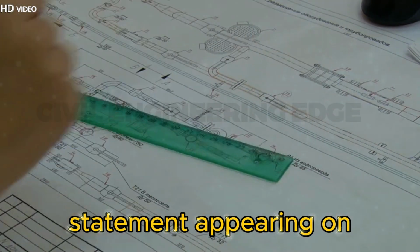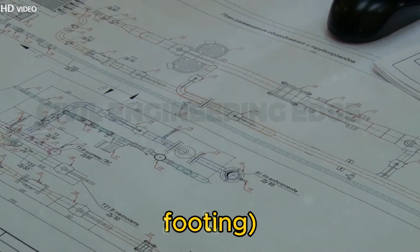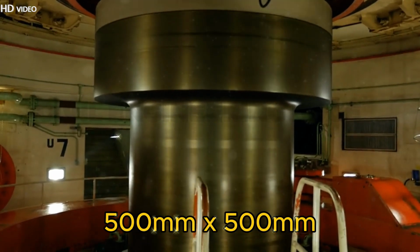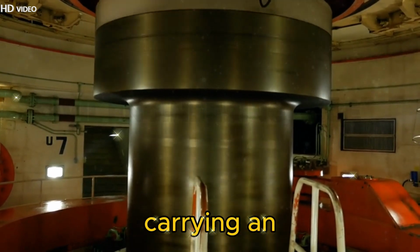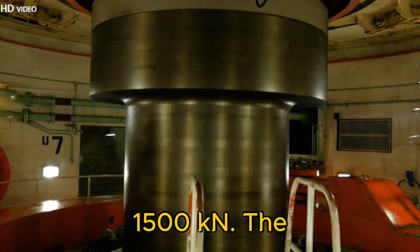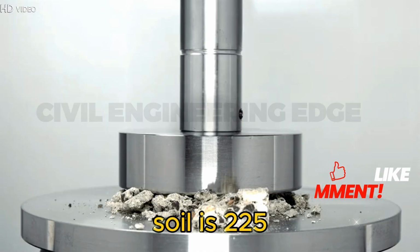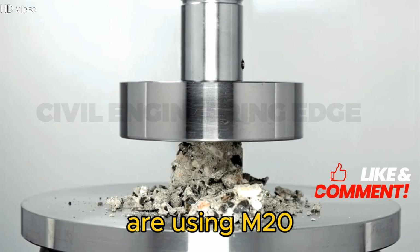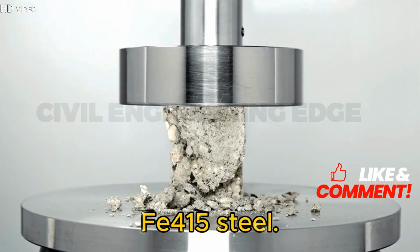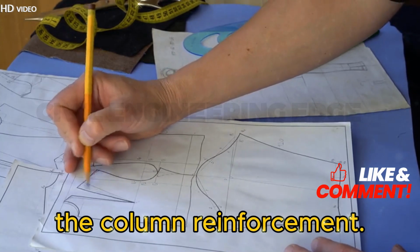Visual: problem statement appearing on screen with a 3D model of the column and footing. We have a 500 millimeters by 500 millimeters square column carrying an axial load of 1,500 kilonewtons. The safe bearing capacity of the soil is 225 kilonewtons per square meter, and we are using M20 concrete and Fe 415 steel. Let's begin by designing the column reinforcement.